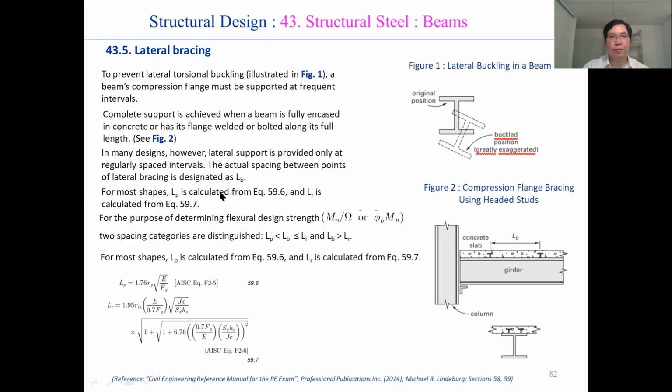So Lp is the actual spacing between points of lateral bracing. For most shapes, Lp is calculated from equation 59.6. Okay, and Lr is calculated from this equation.